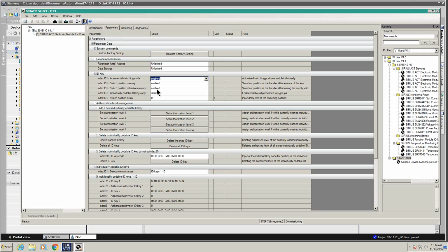Like if you wanted to go directly to output 3, with 0 in there, it would actuate 1 and then 2 and then 3. And they would physically come on during those transitions, where if you left it at the standard 2 seconds, or if you made it 1 second, it would give you a chance to change those positions without actually activating that output. Okay, hopefully that is understood.